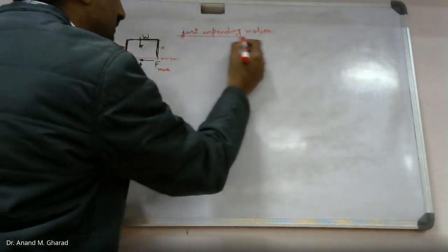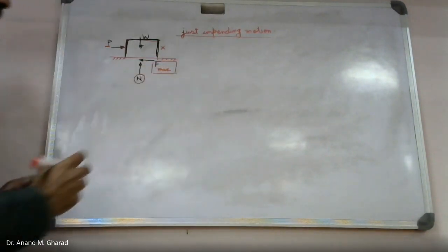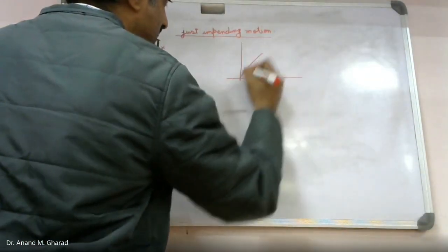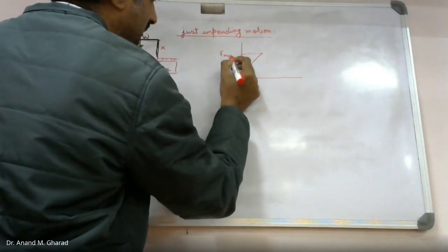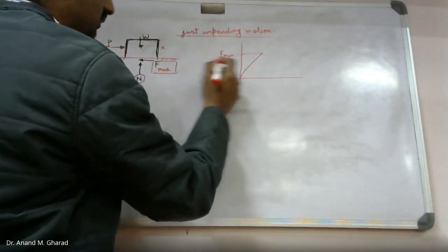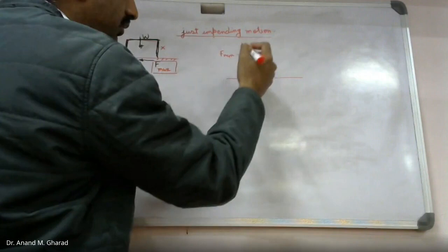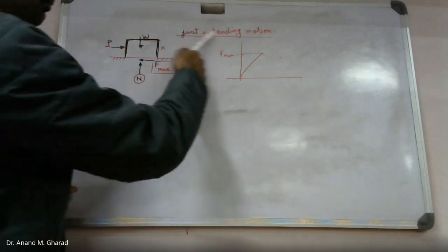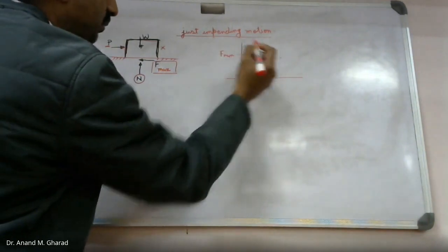When this condition arrives, only then will this frictional resistance become maximum. Just remember that plot. This is the value for F max. What is happening at this value? The force which we are applying is of that order that beyond it the motion of the rigid body will start, or the impending motion will start. Okay, so F max is arrived at this point.